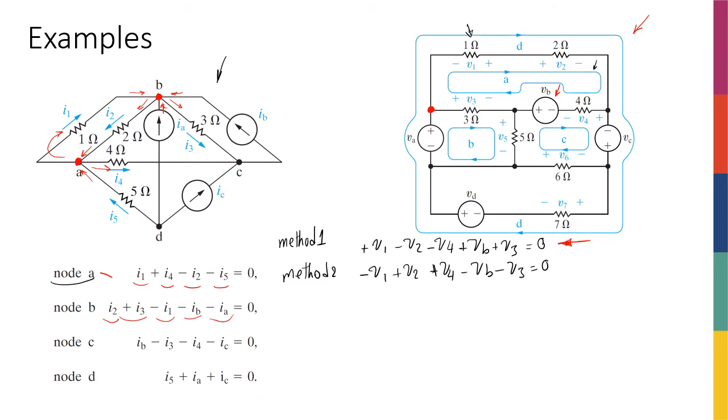So when I go from the negative terminal of a voltage source to the positive terminal, my potential goes up. So I would like to be able to write a positive VB, not a negative one. It's just more intuitive, more connected to reality. But mathematically, as you see, they're not different. So just use whatever you're more comfortable with and then stick with that convention. Do not change your convention from time to time, or you're just going to confuse yourself.